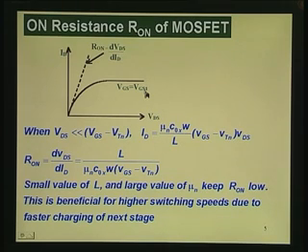So, here you can see this curve is linear in the initial portion, and that linear portion has a slope which is actually delta Vd by delta Id. Okay. That is the resistance. So, this change in voltage divided by change in current, which is the inverse slope of this, is actually the on resistance, the resistance of the device when it is just in the on state. Okay. That is what we are saying here.